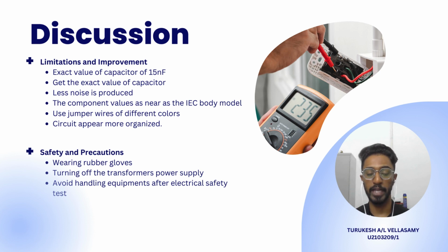Discussion on limitation, improvement, and precaution. One of the limitations we observed during designing the self-designed measuring device is to find the exact value of the capacitor of 0.015 microfarad, which is the standard value from the IEC standard. This is because we are unable to obtain the exact same capacitor value from the medical electronics lab due to component constraints. We achieved 0.015 microfarad with two 0.01 microfarad capacitors connected in series, and another 0.01 microfarad capacitor connected in parallel.